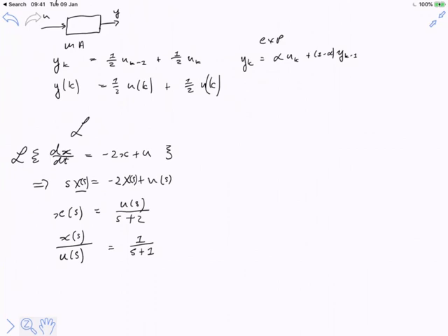And you understood that that meant that this system would act on its inputs in a dynamic fashion, not just simple mathematics, which would cause outputs. So that's the one place where we use the Laplace transform: we used it to act on mathematical descriptions of systems to get a function in S that described how the system worked, which we call the transfer function.